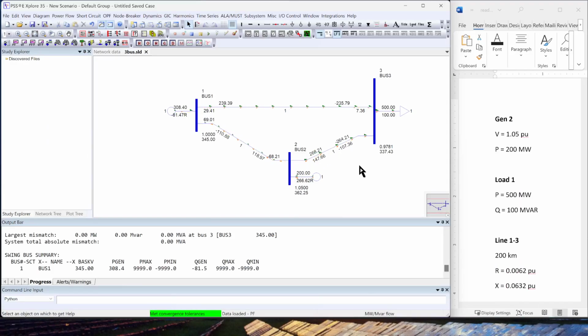So this is how you create any power system network from scratch. I hope this gave you a good idea, and there are a lot of different components your system may need. For example, you have more induction machine, shunts, then your FACTS devices where you define your SSSC device, STATCOMs, or even the HVDC lines.